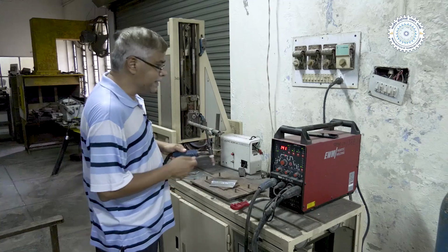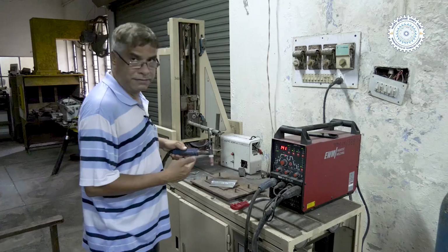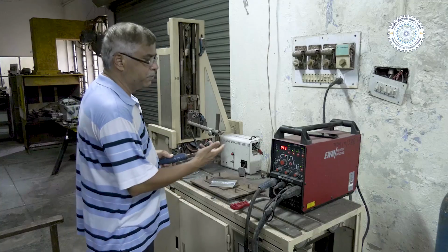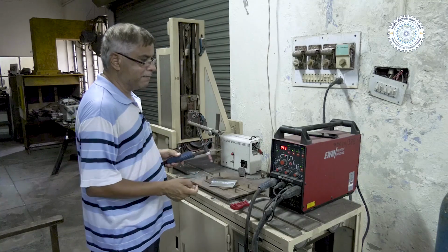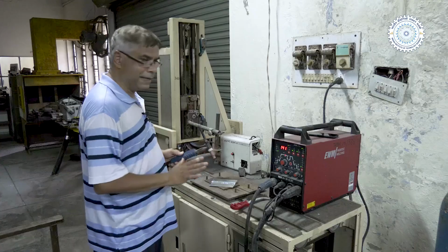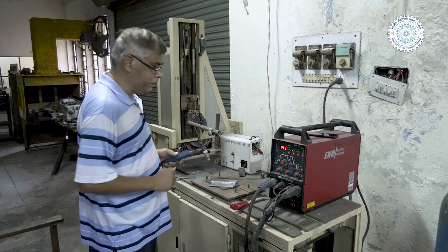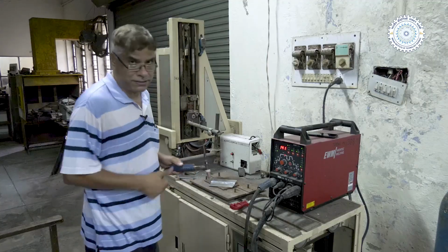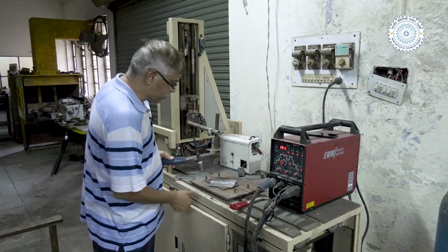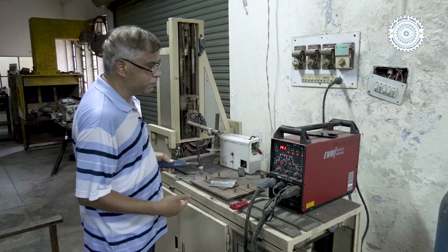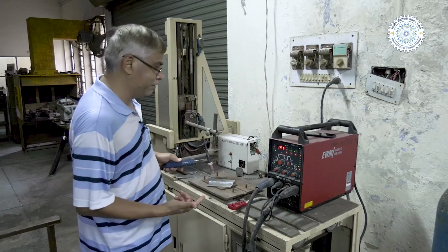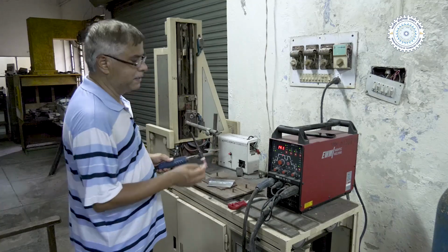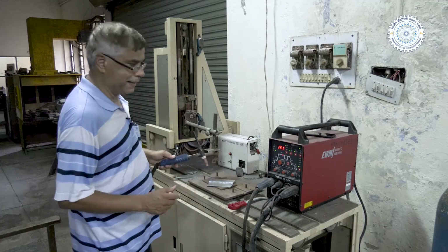Now we will see the step by step demonstration of the TIG welding process. As with any welding process, we have to set the current and the voltage in light of the electrode and the heat to be generated for development of the weld joint, in light of the thickness of the sheet to be joined. The thicker the sheet, the greater the heat input required, so the greater the current setting that we need to use. For the tungsten electrode, the voltage is normally fixed, like 12 or 15.